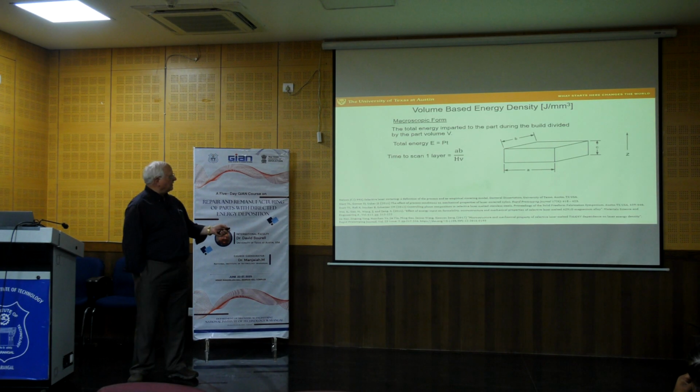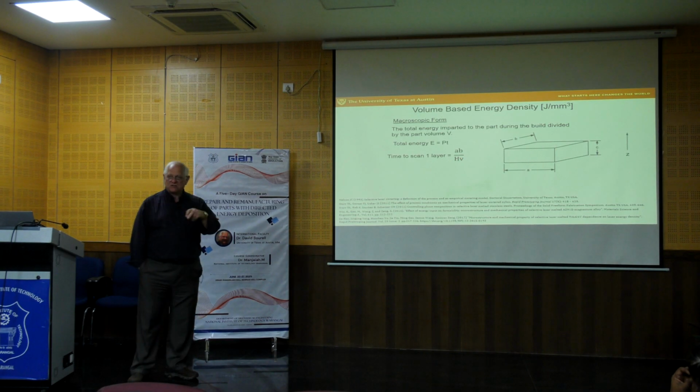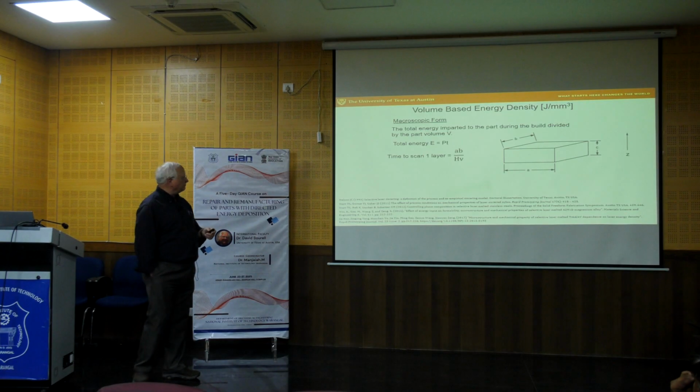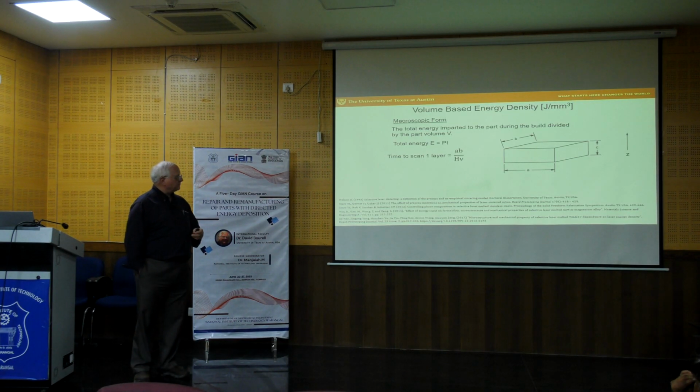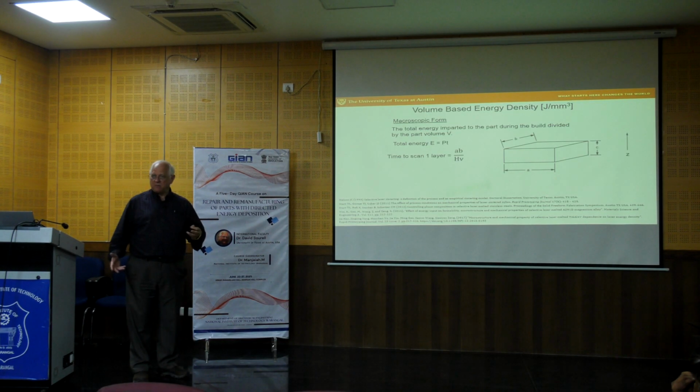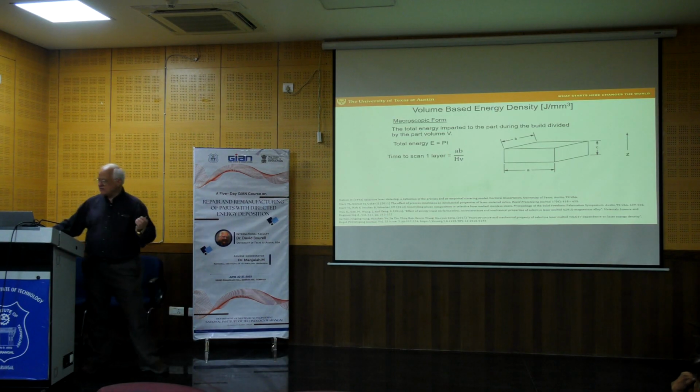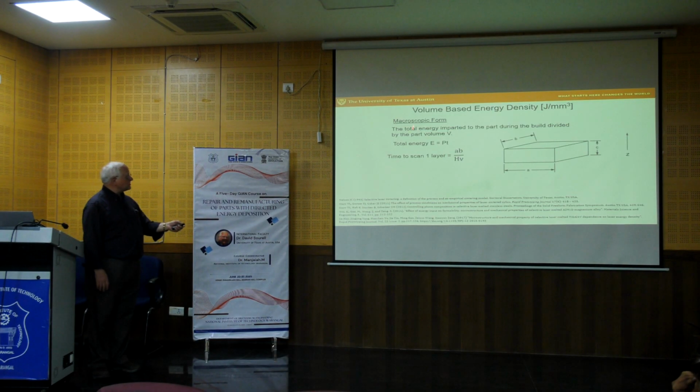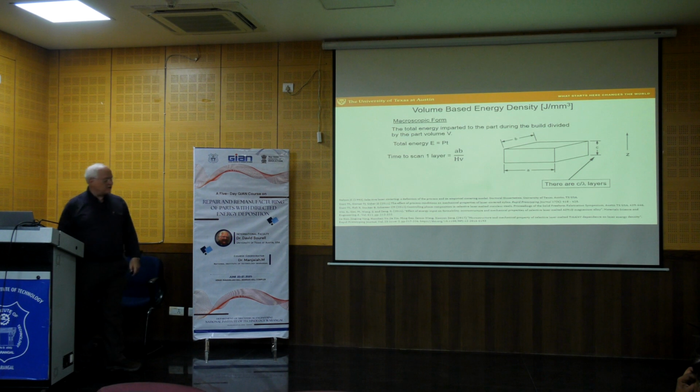So basically, the scan speed times the hatch spacing tells me, on an area basis, how much time is required. So this is the time to scan one layer. Then I have to determine how many layers there are. That's relatively easy to do.